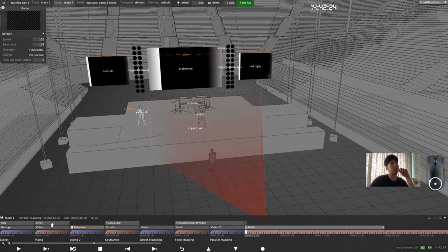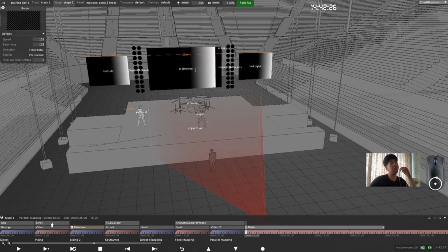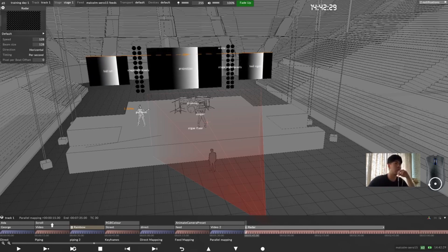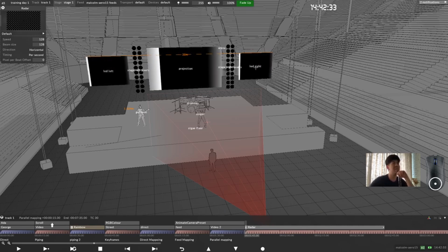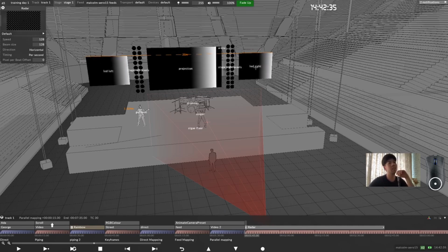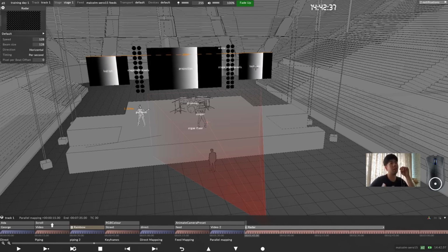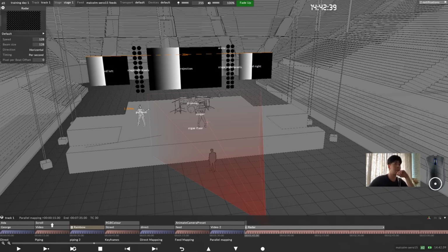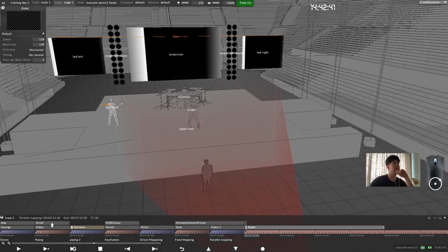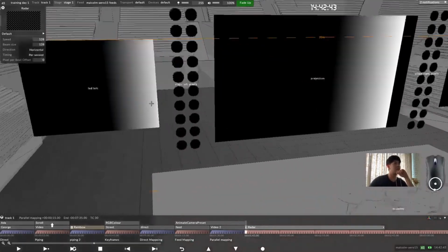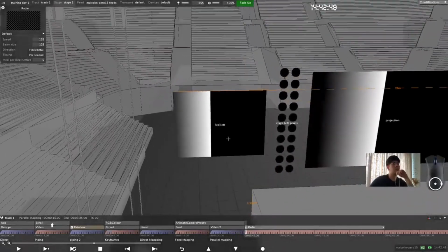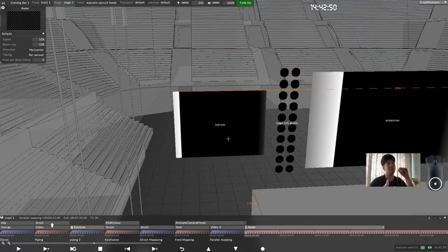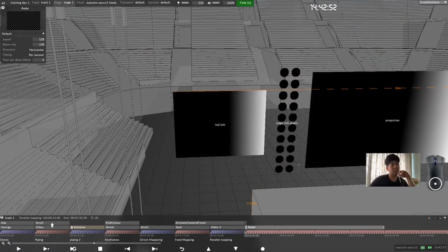Unfortunately, I don't have two projectors here. Otherwise, tomorrow I can show you guys. But by sending white and scanning across the area, you can actually see the blend area, whether it is done properly or not, as well as the alignment. This is very good for LED walls, because you can see whether your actual setup is misaligned or fixed nicely.